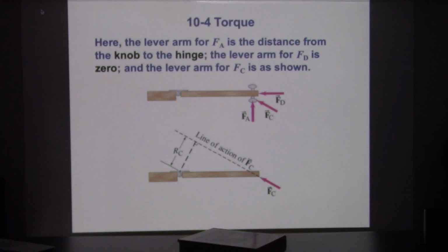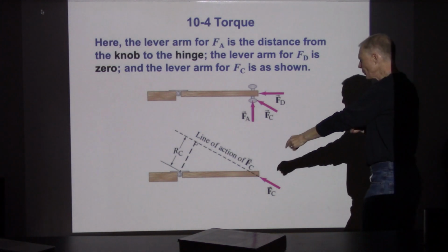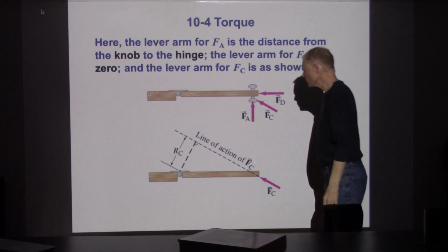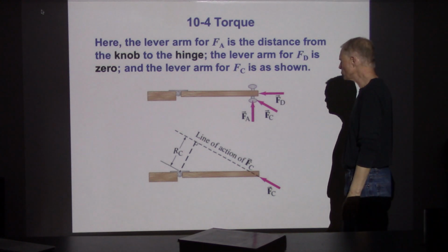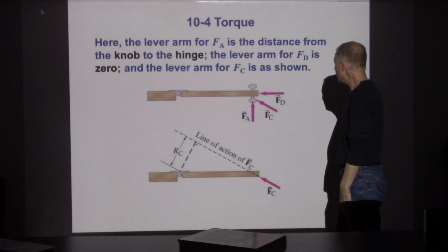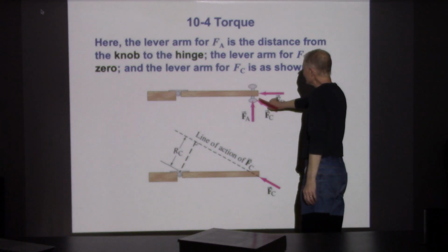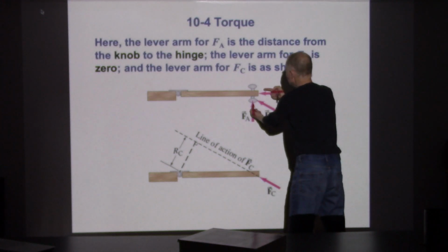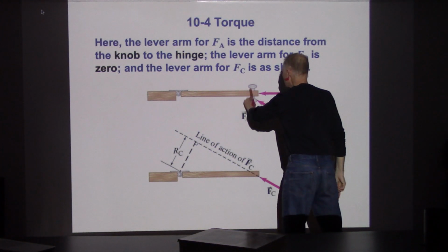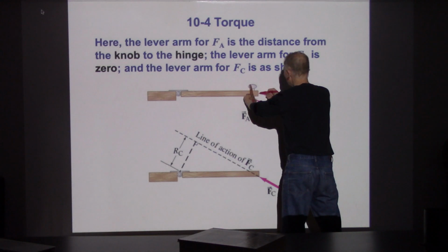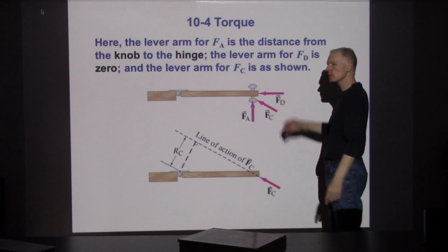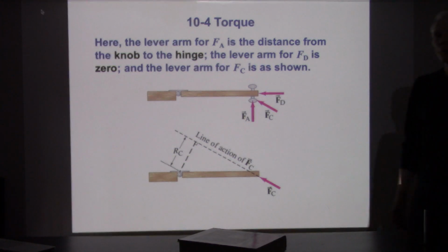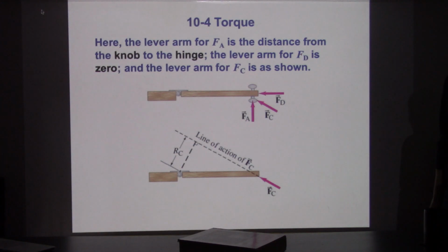So for that, if I want to calculate what the lever distance is, I can do a diagram like this. Now you can do a diagram like this, which I always feel like requires trigonometry, maybe doing a sine or cosine here or there. I actually think it's easier to take the force itself and divide it into perpendicular components and parallel components, and then I just ignore the parallel components, because they are not going to provide any torque.